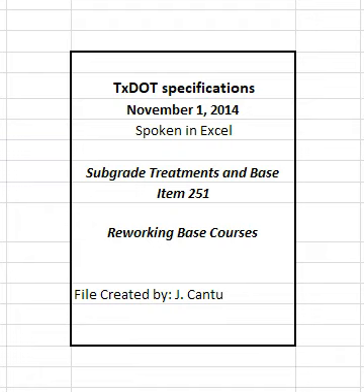4.3.1 Ordinary compaction. Roll with approved compaction equipment as directed. Correct irregularities, depressions, and weak spots immediately by scarifying the areas affected, adding or removing approved material as required, reshaping, and recompacting.